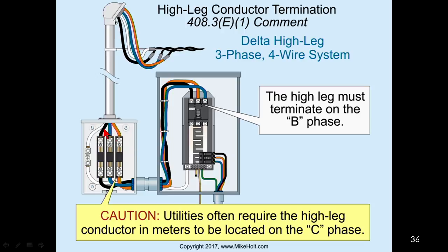But if it was black, red, blue, and you put a transformer and you're trying to now get from a 208 volt system, we're going from 120 to 208, I need to get 240 volt rated equipment, and I needed a grounded point on the secondary side. Well, then I would go from 208 primary, and I would then go to the secondary, because the transformer primary could be lower voltage going to the higher voltage going out in that particular case. Well, then I'd have a high leg on the output. So the high leg is originating from the power supply.